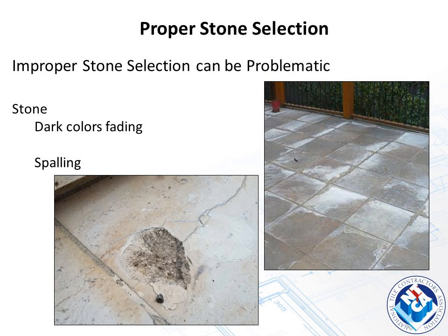And for that matter, some dark colors can fade. If you put a polished black marble on the exterior of a building facade for that matter, the odds are pretty good in a few years, if it's taken a lot of UV, it's not going to be a shiny black marble anymore. Make sure that the color you're using is recommended for an exterior.